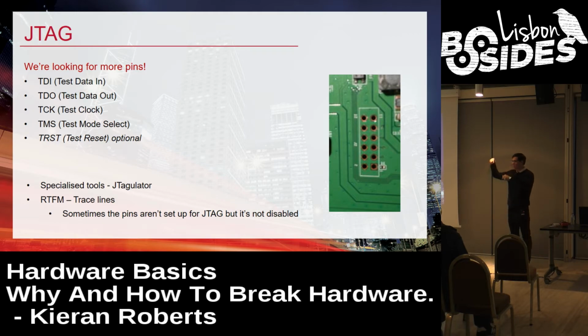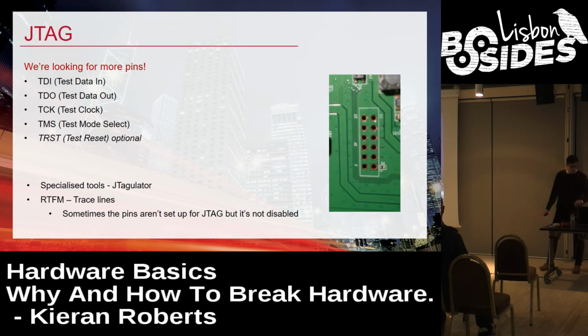Even if you don't have a handy pinout here, often you may have seen PCBs with wires soldered seemingly randomly to the board. If you can just follow the trace from the pin to where it goes on the board, then you can solder straight onto the trace, using some super fine wire like speaker wire, which is the best thing. So that's JTAG and firmware. Like I said, we don't have time to do it properly, but there we are.